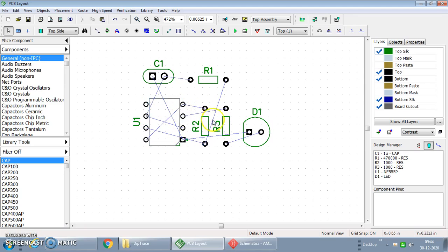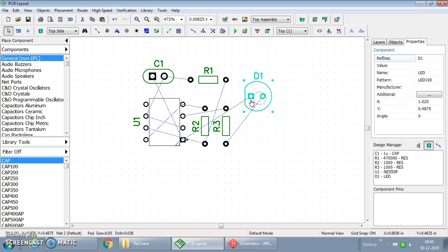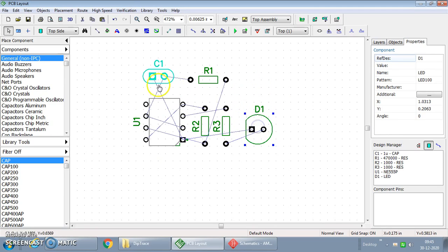Then the reset pin, accordingly these pin connections are made. This is possible with an automatically designed PCB. So now this is the layout we are getting. These are the connections, how it looks. Now actually we can adjust it manually. The software has done the adjustment as per the schematic designed by us.